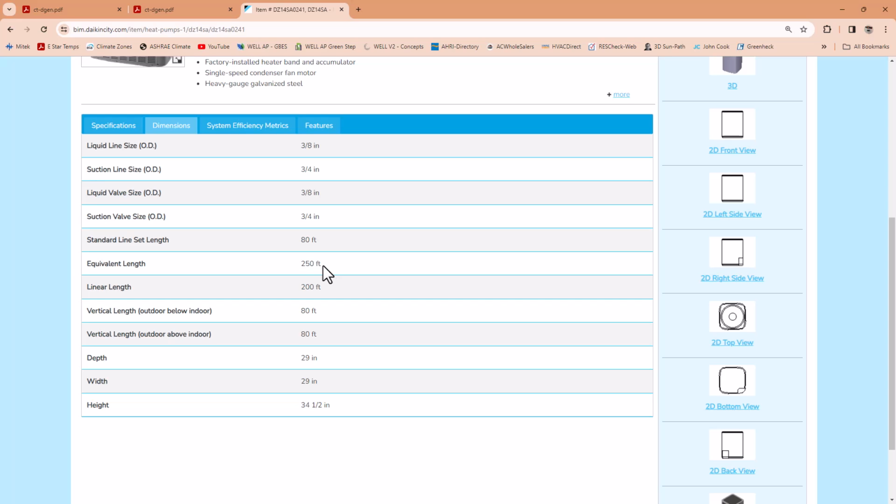The issue, when this becomes very interesting, is when you have the unit at the basement, and sometimes you have to run 30 feet this way, and a lot of elbows go up to the roof. So you are affecting the efficiency, I mean the performance. So that is what I usually check.